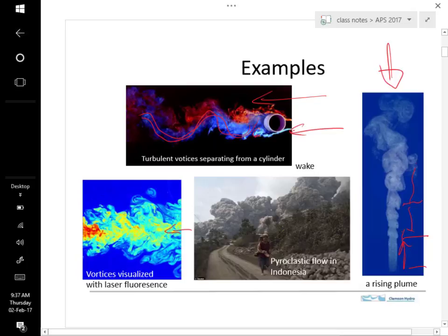But then once you get up into here, the flow is breaking up, and we have this much more complicated pattern. And as that happens, you can see that that's also causing mixing. As this plume changes width here, this is the width that it starts out, and as it progresses up, we have an increase in the vortices and spreading as we get mixing of the plume with air, dilution of the plume, and a dispersion process.